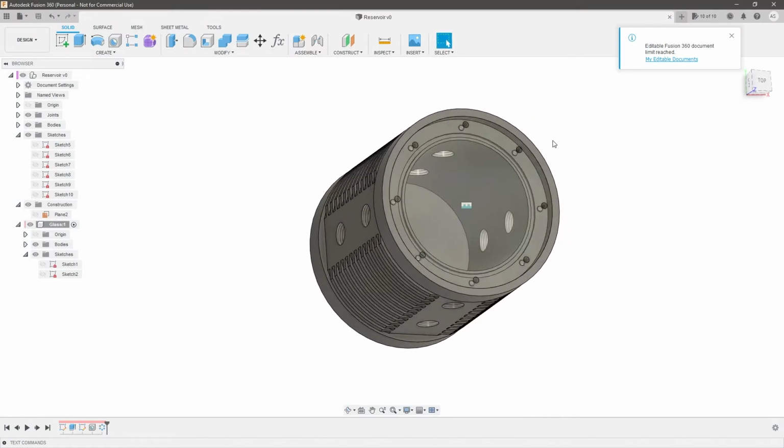Okay, now that we have that saved, we have the option to either utilize this as a standalone subassembly of two components, or we can insert components into this design and further add to the subassembly. So right now, I'm going to go ahead and further add to the subassembly. So we still have kind of a bottom up, but I'll show you what I mean.